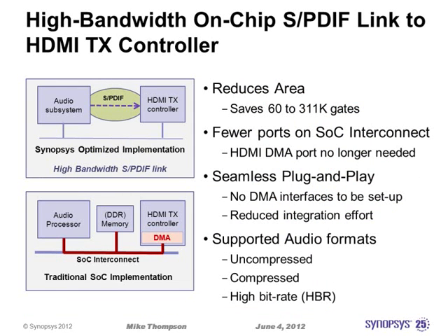One of the things we did do is, of course, Synopsys offers an HDMI interface as part of our interface IP. And we have access, obviously, to the inner workings of HDMI as well as the inner workings of the audio subsystem. So we actually created a back channel, and that's what's on top there, where you can directly output from the subsystem into the HDMI interface and literally bypass the bus.